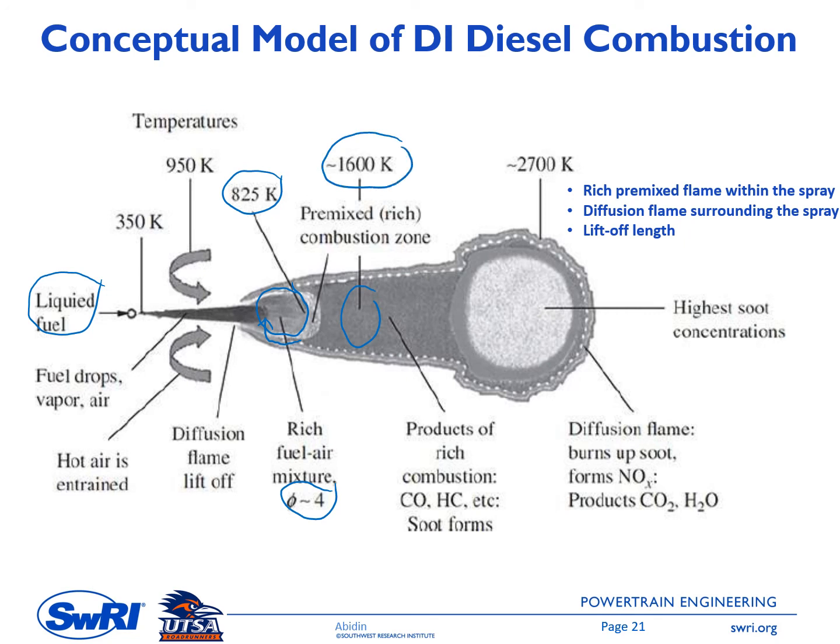At this temperature there will be a chemical process that releases maybe 10 to 15% of the chemical heat, and then this partly combusted mixture will move farther down, and then there will be a block of hydrocarbon fragments here, and because of this rich mixture combustion and also additional heat transfer from radiation of the surrounding gas, it will form particles which are usually called soot.